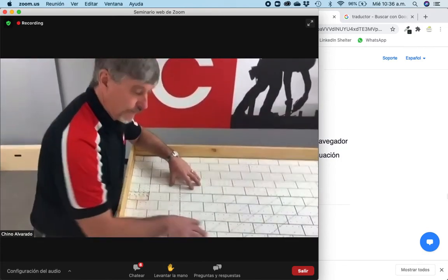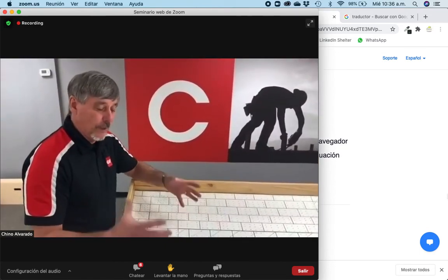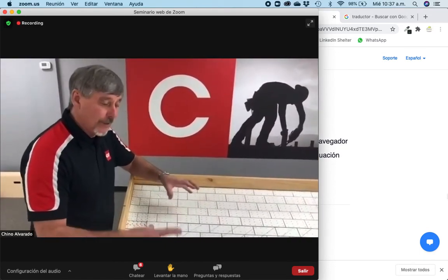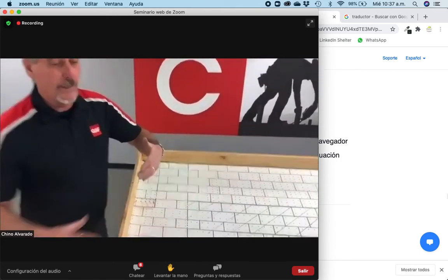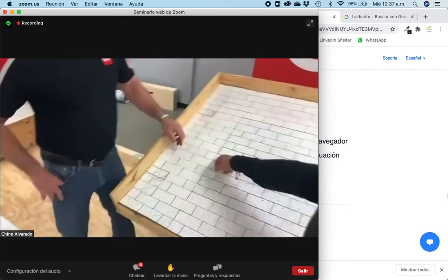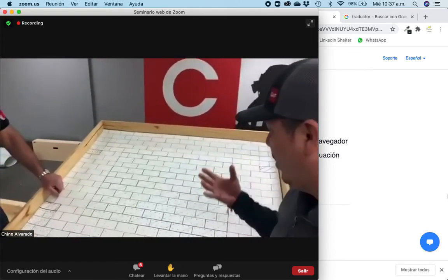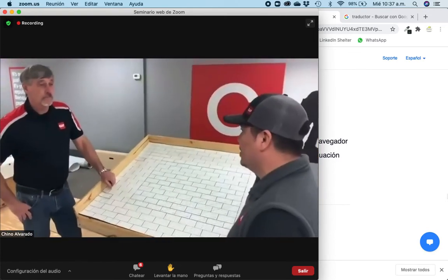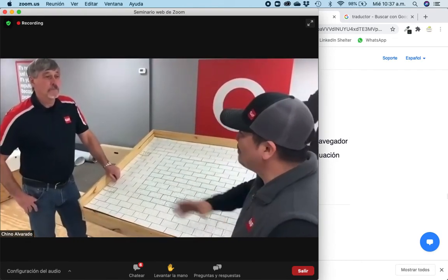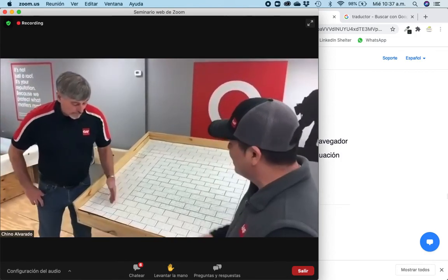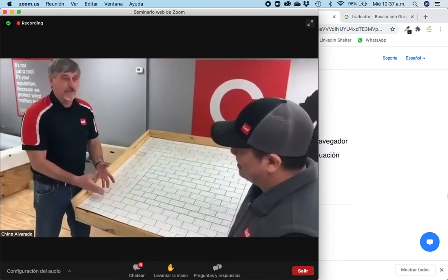And you can tell this looks really busy. I understand that. This is how many fasteners, with the way this equation worked out for this mock-up. This is our fastening pattern, how many screws we're going to need for each board. Now, pretty much right here, we're constantly splitting boards all the way across this entire roof. Once again, guys, it all is going to depend on your guys out in the field, because to them, it might be simpler. You know what? I'm just going to not split it and go with that full board. Well, then it's going to throw your L off. I'm supposed to have an L, but it doesn't look like an L.